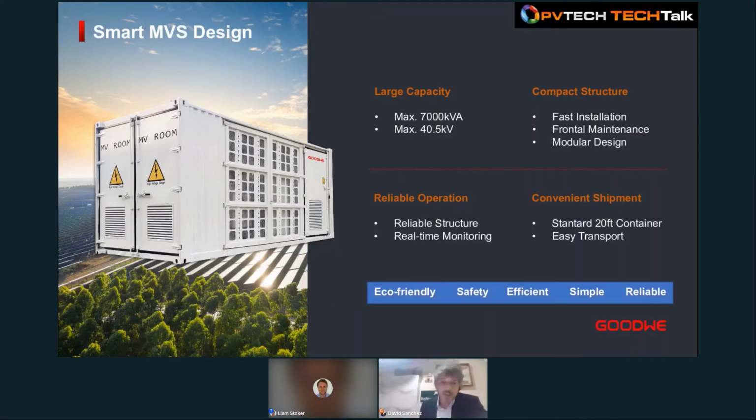Our transformer station, so we deliver our inverters together with our transformer station. Just roughly to speak here for a second. So we are bringing a 7 MVA transformer station, which we believe is quite optimal as to Capex and as to design on site, quite flexible with all scenarios. And again, not only 7 MVAs we are bringing, also lower capacity, but we go up to 7 MVAs, which is 28 inverters connected to the transformer, 14 to one winding and 14 to other winding.